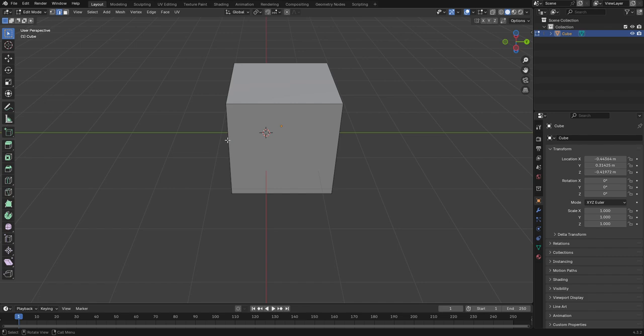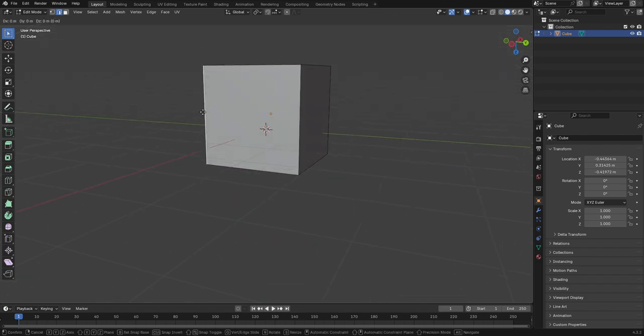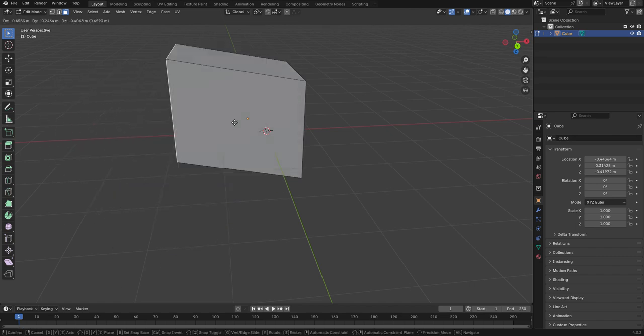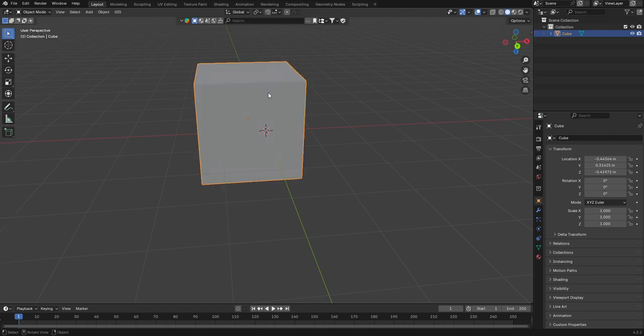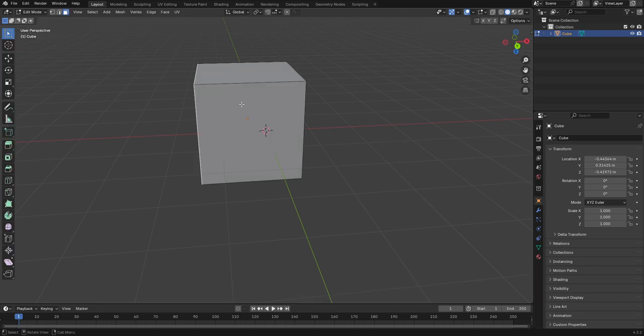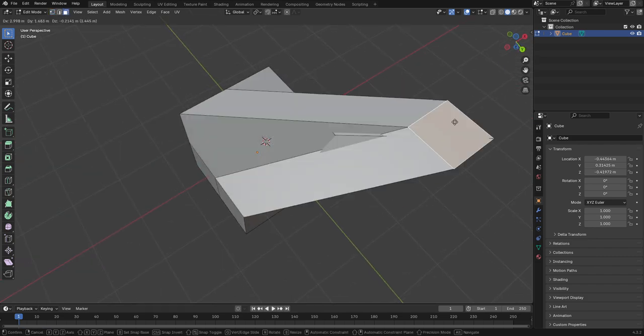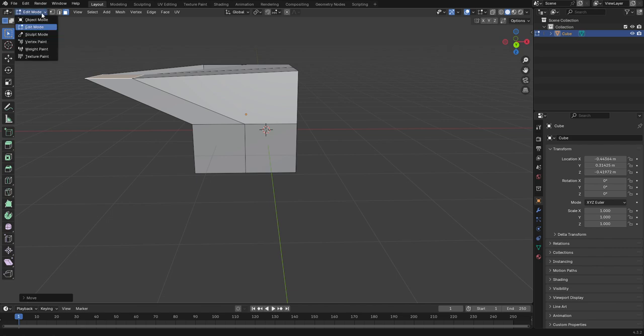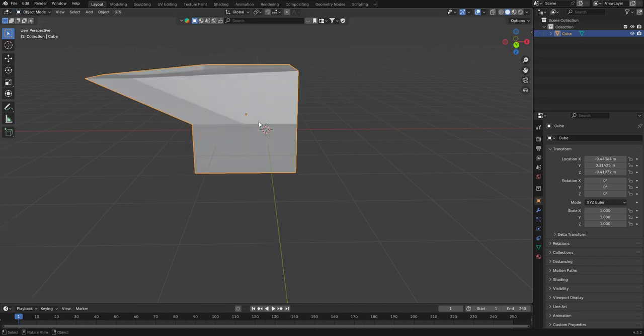This is the vertex. For example, if you just move this vertex like this, and this is the face shape. If you delete your face, it will remove this. Or if you click on object mode and then go to edit mode, select all the vertices, right-click and subdivide, it will be subdivided. And you can manage and edit every face. So this is what you can do in the Blender software.